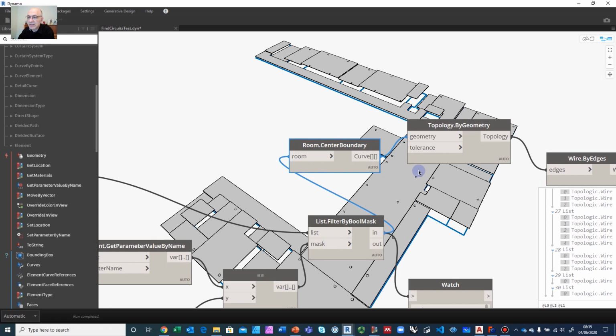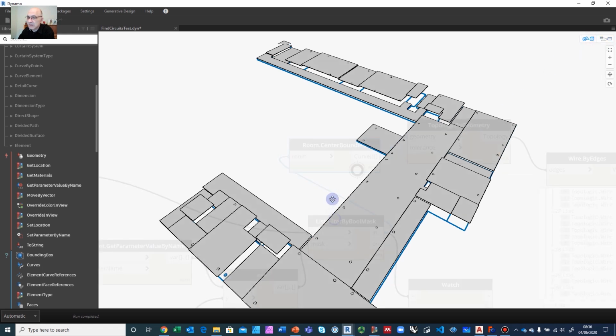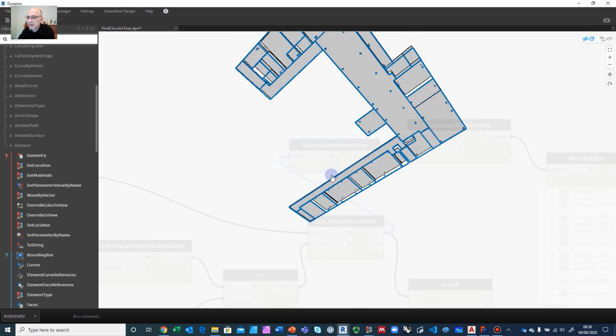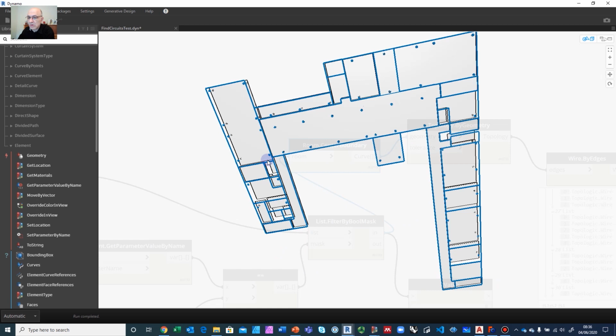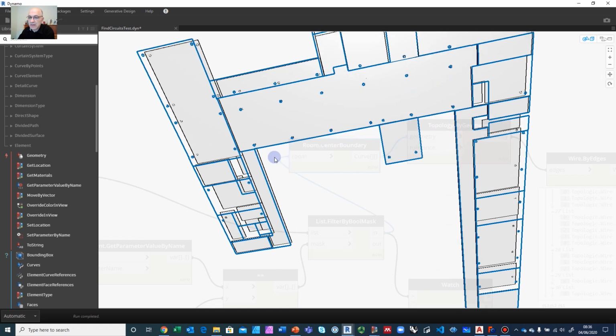So this gives you a drawing that is very similar to testfit.io. So if you know about testfit and how it works and kind of the data, and I've tweeted about it and I have put on the website some workflows that take testfit data and build three-dimensional entities, and you can do energy analysis. I've shown how you can do energy analysis on them, and you can do exactly the same here, because if you look at these boundaries, and apologies if it's not very clear because it's below the faces because I offset them, they are single lines and they are all kind of cleanly trimmed against each other, and rooms share these lines. So once you have this kind of shared edge between a room and another room, you can do adjacencies, you can do topology, you can do energy analysis.